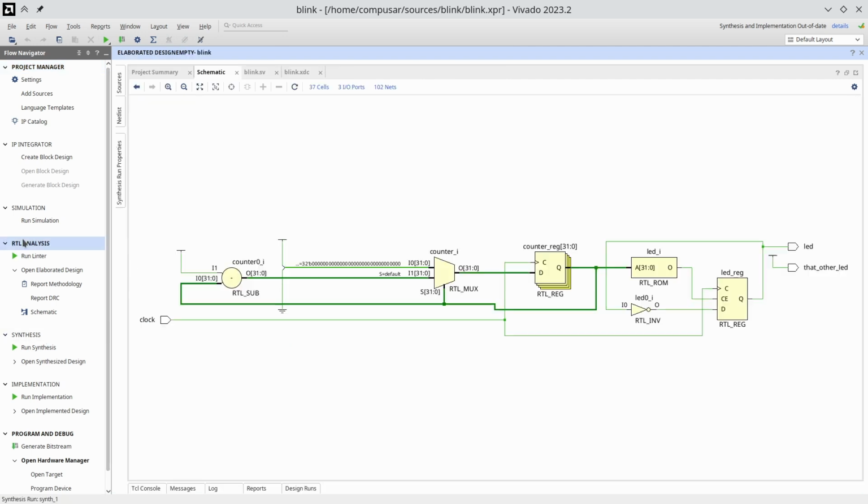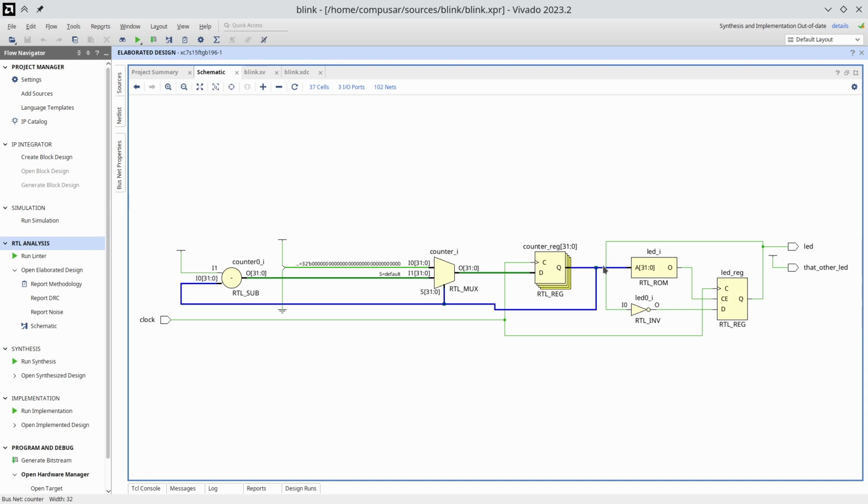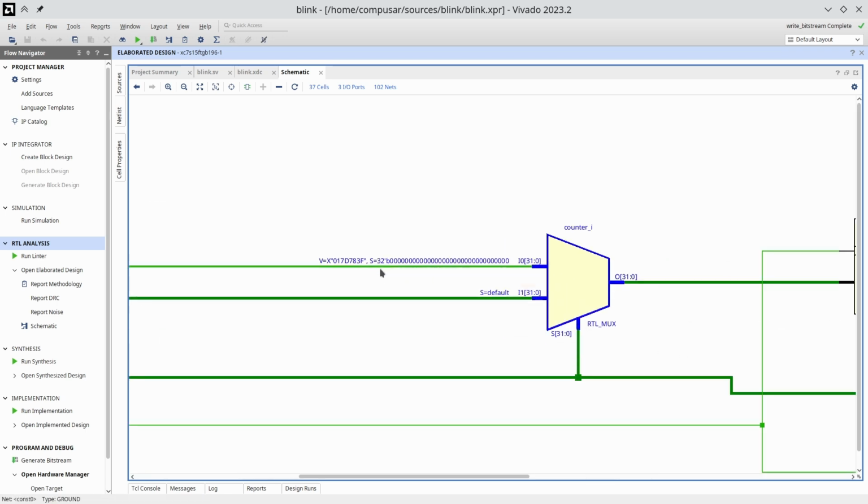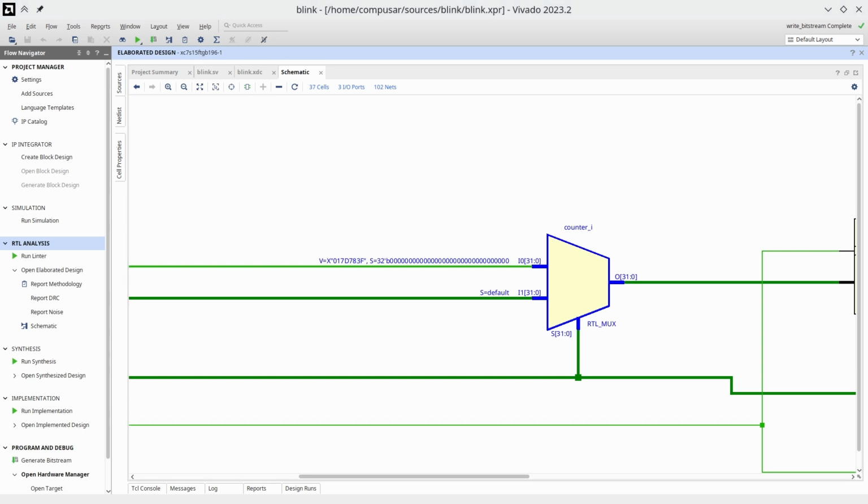We can see that what's being fed into the ROM is the output of the counter register. That, in turn, does not have a visible enable input because we unconditionally update it every cycle. The content of what we update it with changes, but the update happens every cycle without fail. Which brings us to the input of the register. This trapezoid is the symbol for a multiplexer, often referred to as a MUX. It has a selection input at the bottom and multiple data inputs. Based on the selection input, it routes one of the data inputs to the data output.